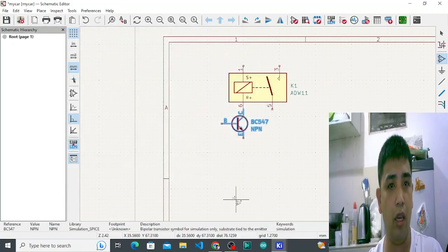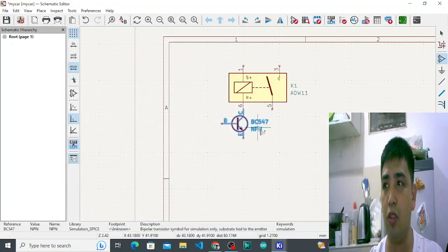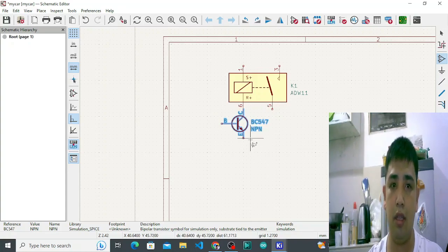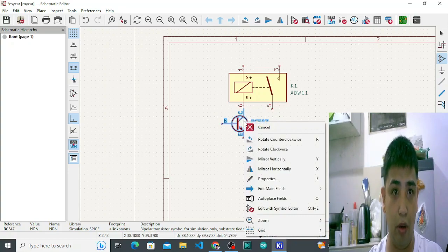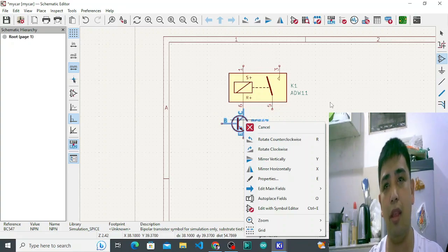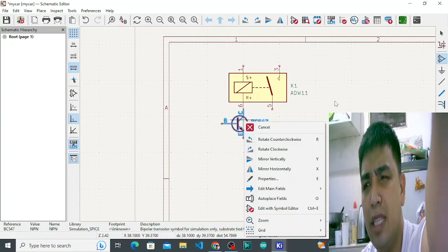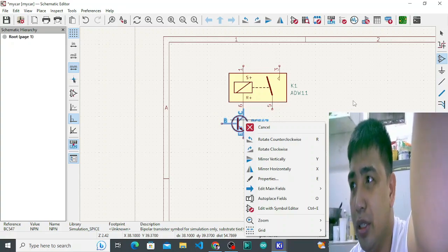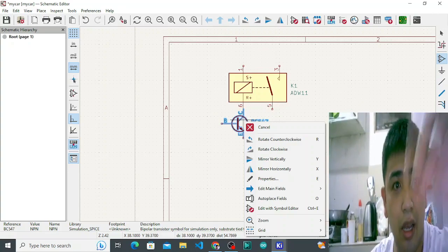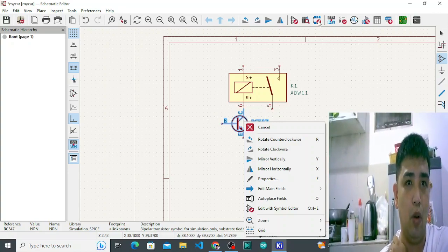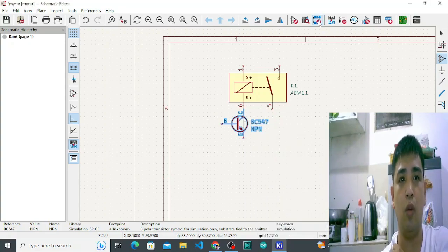And then click OK. And then you see that the name changed already. So yes, that's it. And then the problem is with the footprint, so we're going to assign a footprint, and I will show you some ways on how to do that. You can go here, assign footprint. Okay, click this one, assign footprint.